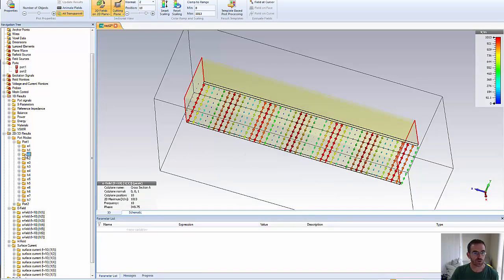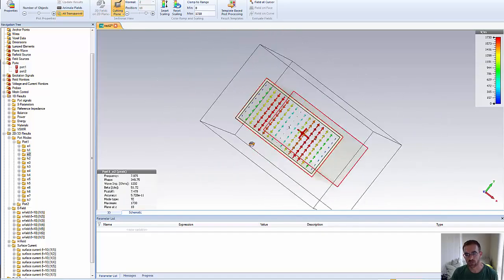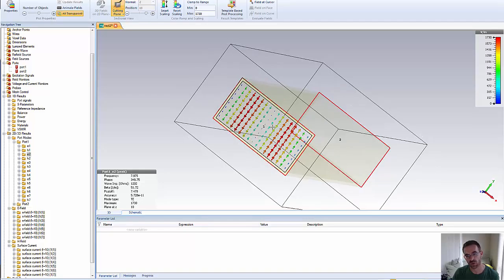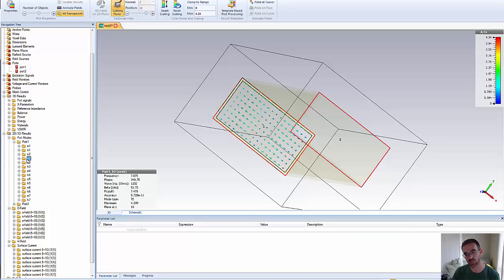Let's take a look at the second mode. So it turns out that the next mode has a structure which is given like this, where we see constant variability in the y direction, and we have one cycle of a sine wave. So we go from 0, maximum negative, back to 0, maximum positive, back to 0. So we recognize this as the TE20 mode. We would expect to have x-directed magnetic fields that have the same sinusoidal shape, and we see that.